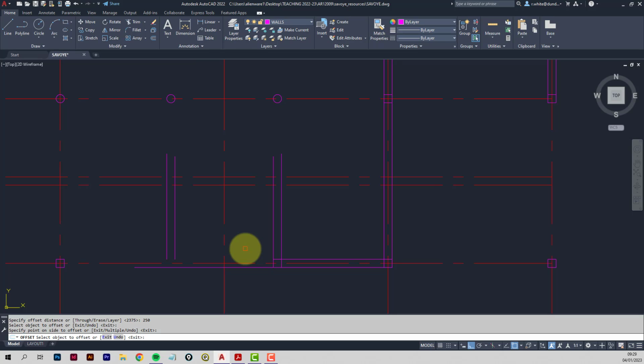Okay, so this is a bit more like regular design drawing. We end up with a bit of a mess, things on wrong layers, things that don't meet. We need a bit of tidying here. So press escape. I'm going to try and use the fillet command for all of this. So fillet, check that the radius is 0.